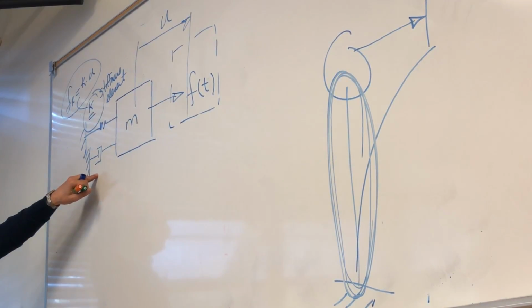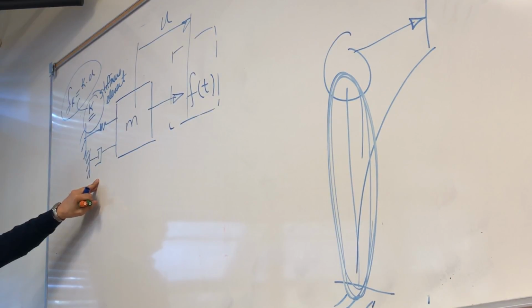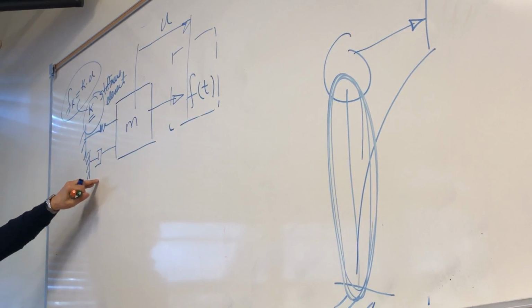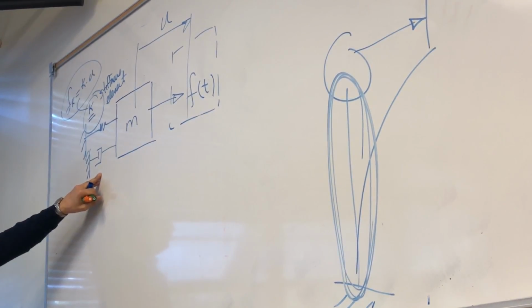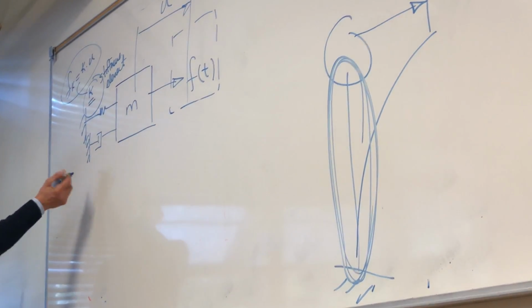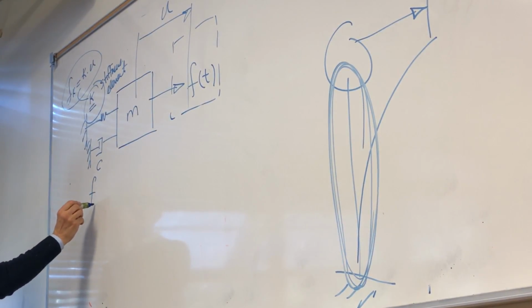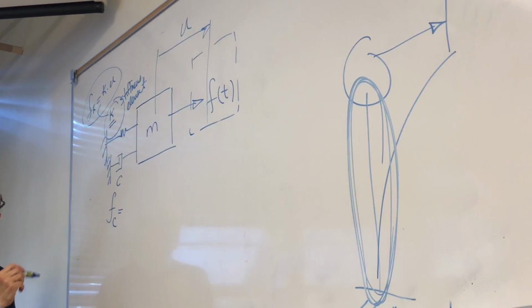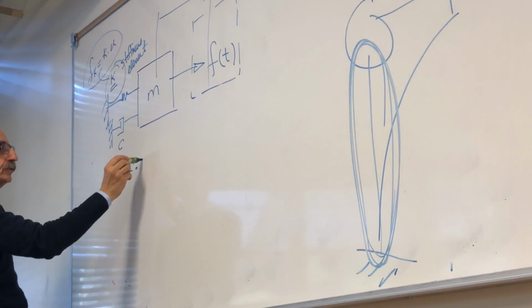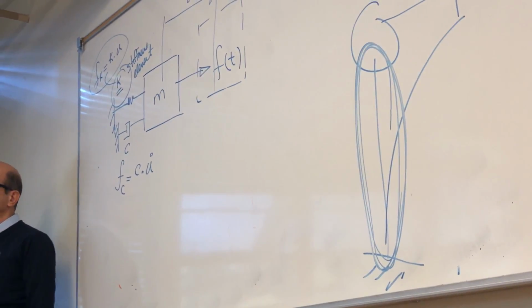We call that an energy absorption unit, or a damping unit. In order to represent this force, we just simply fudge it, because we cannot fully describe it mathematically in a simple way. So we describe it based on a very simple and rough assumption: that this force, which we call the damping force, is proportional to the velocity that this mass experiences.